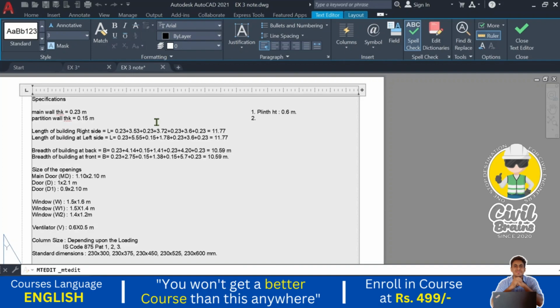So that's why we have taken 0.6 meters as the height, and the requirement of the client is also the same. He wants a little higher foundation, so that's why we are considering 0.6 meters. Okay, the minimum should be kept as 0.45, not less than that. So we can keep 0.6 meters here. Okay, so next we have considered plinth width.